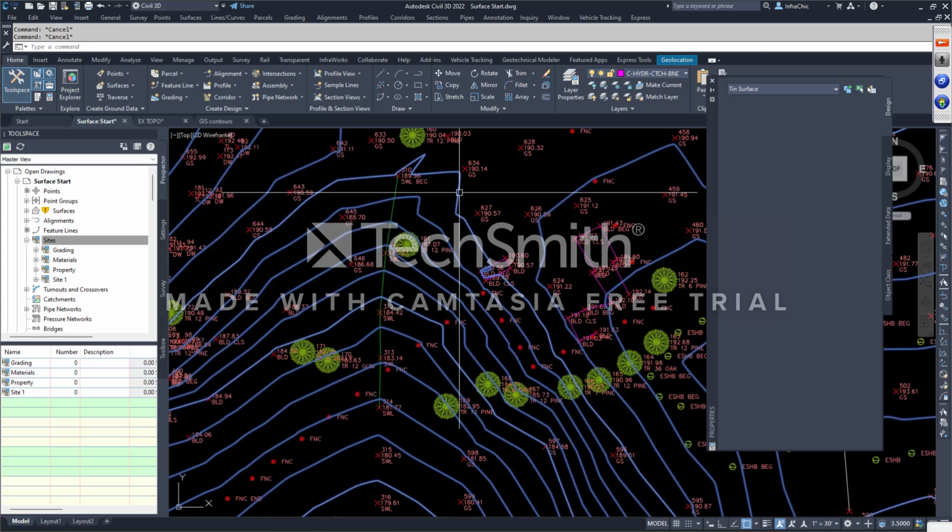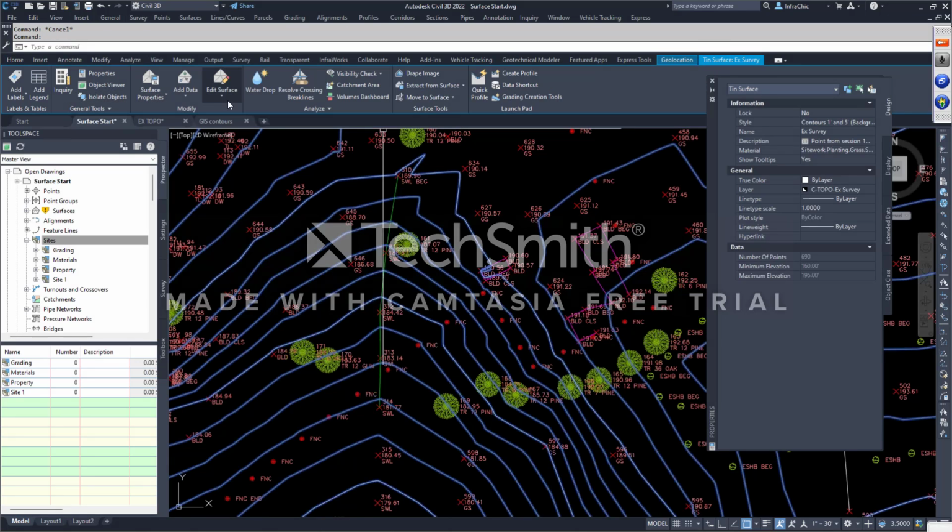Oh, yes. When I select a surface and on this awesome ribbon that comes up, if I need to bring these contours out and turn them into polylines, but I want them to also stay in the surface at the same time because somebody doesn't have Civil3D, somebody has plain Jane AutoCAD or MicroStation, I don't know. Anyways, they don't understand XML. They just want you to give them polyline contours.